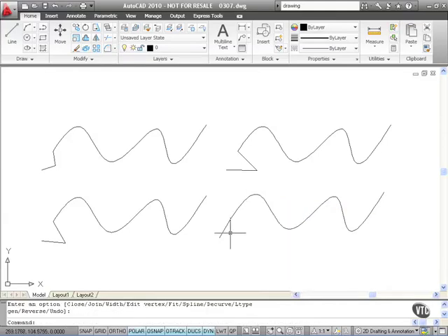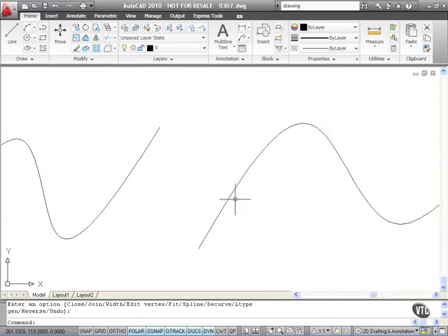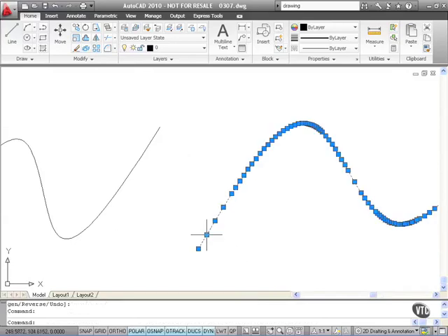Let's just zoom in a little bit now on the end of that new polyline. Click there, click on a grip, look what happens. It comes out as an arc. So the polyline now has been converted into arc segments using the PLINECONVERTMODE variable. So as you can see there, splines are now so much easier to edit and convert into polylines. That's a new feature of AutoCAD 2010.